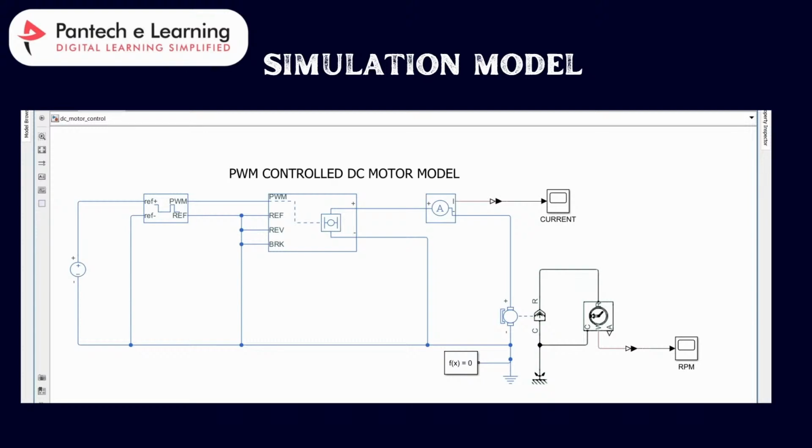So how does this PWM work? Imagine you have a light switch. When you turn it on, the light shines brightly. When you turn it off, the light goes out. Instead of just leaving it on or off, you start flicking the switch on and off really fast. The time the switch is on compared to the time it's off determines how bright the light appears. The same idea applies here.